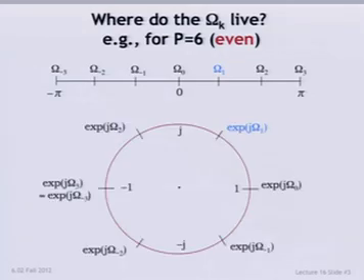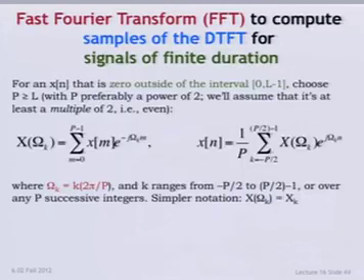Or you can think of them as points on the unit circle that correspond to each of those exponentials that appear in the Fourier transform definition. And we then recover the time domain signals just from those samples. Okay, and really what's driving this is the fact that the signal is 0 outside of a finite window.